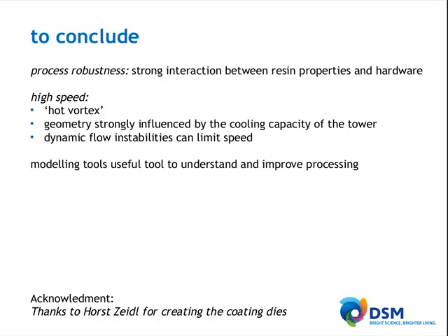With large deformations of the interface using the wet-on-wet process, can you confirm that the wet-on-dry process is much more preferable for the coatings application? So what I've shown here is that the two fluids are flowing together through the coating die. In a wet-on-dry system, it's not that different. It just depends on the cure state at which you enter the secondary coating die. So you have to make sure that you're getting to a sufficiently cured primary in order to not have these type of deformations. It's different because now conversion or the partial conversion of the primary plays a role, but it's also very similar.